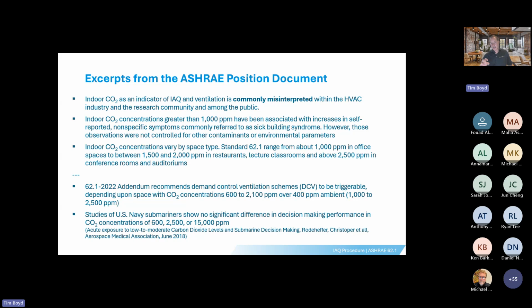That aside, the NIOSH level is around 5,000. So 5,000 for over an 8-hour period is what most people agree not to go above. But that's far higher than what you're probably used to in the designs that you either learned on or that you've tried to design to, with very low levels of CO2 that require very high levels of outdoor air. This kind of puts that on its head and says, look, you don't need to do that.